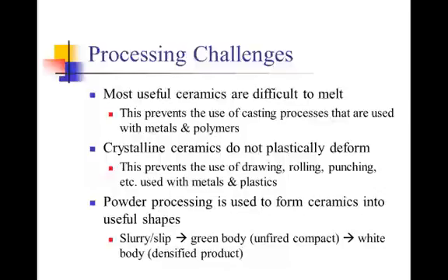And the problem that occurs is that we talked about earlier in the class packing factors, and you know that if you have some particles that are rearranged and packed back together as efficiently as they can be, that there will still be some empty space in between these particles. And so then your ceramic that's been reshaped is very porous, and you need to try to eliminate the porosity or fill in the porosity some way. And so that's powder processing, when we grind the ceramic into a powder and then reshape it.